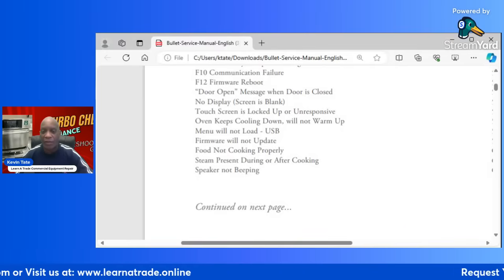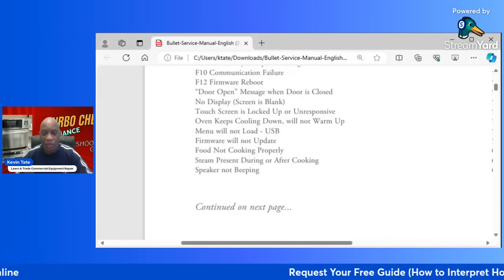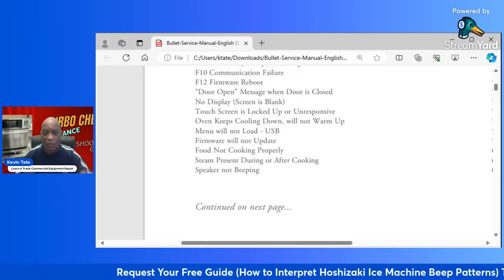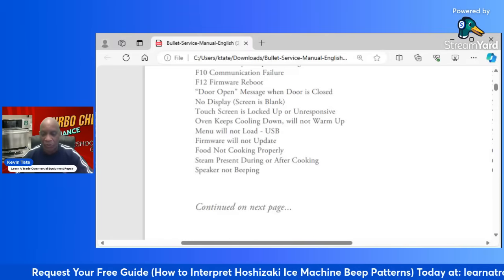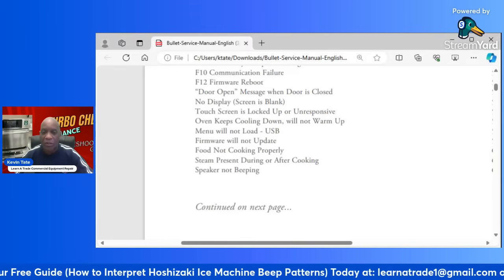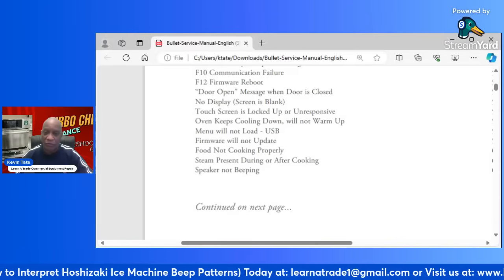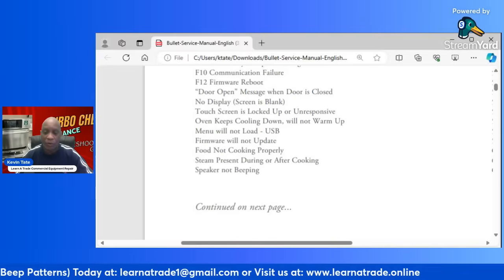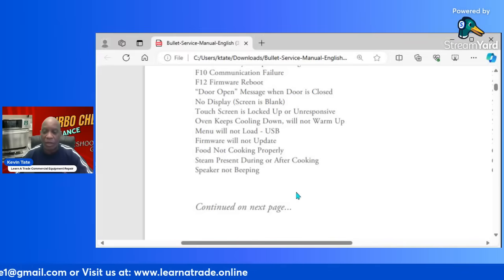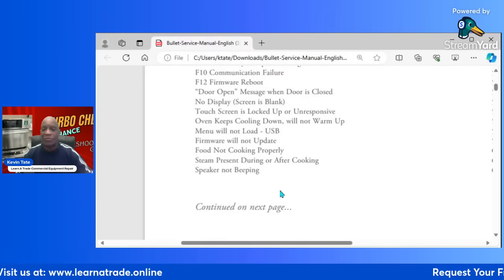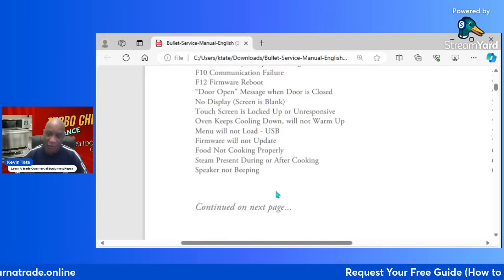If the volume's all the way up, then you have a faulty speaker, or a bad connection on the little white terminal that the speaker connects to on the board. In that case, you can fix that connection, or replace the speaker completely, and then readjust it for the proper volume that is comfortable for them.